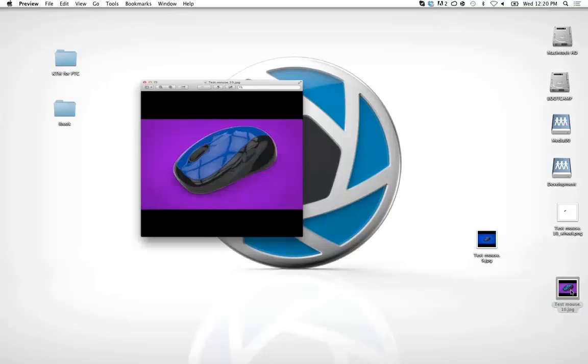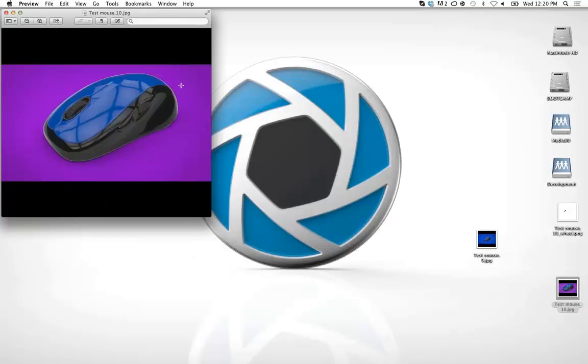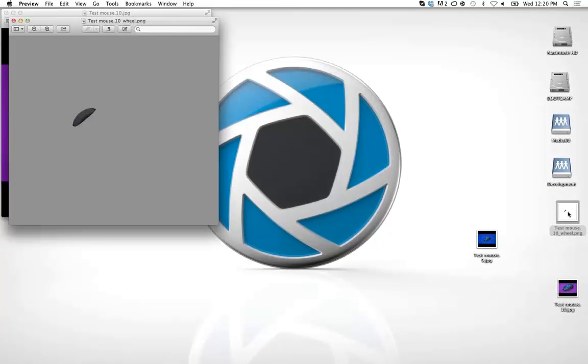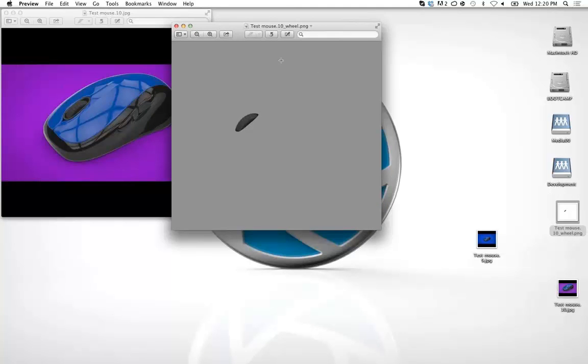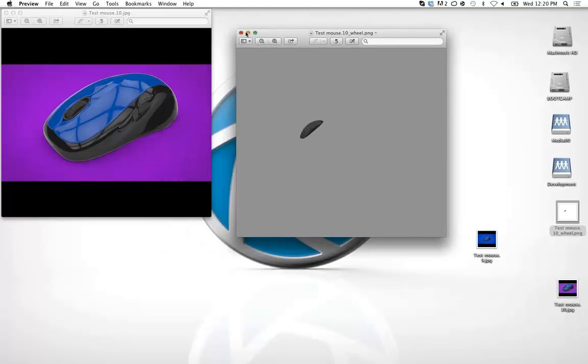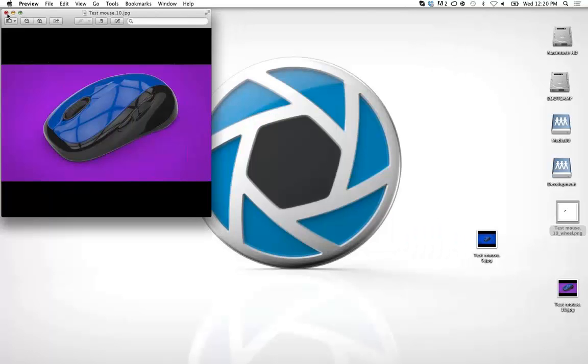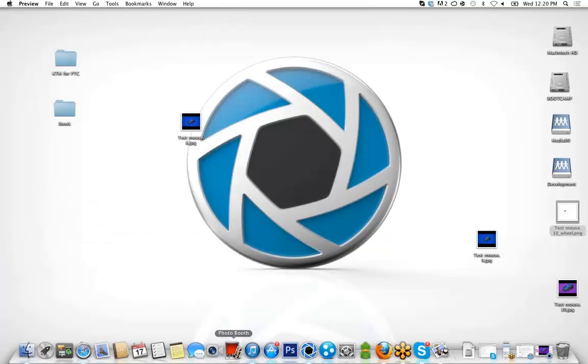This gives you one rendering of the entire image, and then, if you have the render layers on, here it is, just the alphaed out wheel. So if you want to do some compositing or fine-tuning in Photoshop with just a little bit of it rendered, that's how you do it. You use render layers. I love using render layers. It's like my favorite thing. But again, it's a more advanced tool, so I didn't want to get into it right away, but it was fast enough for me to explain right now. So if you want to use it, that's how you do it.